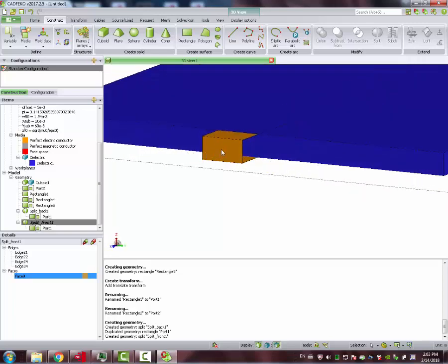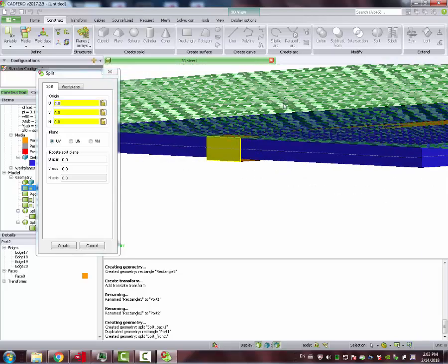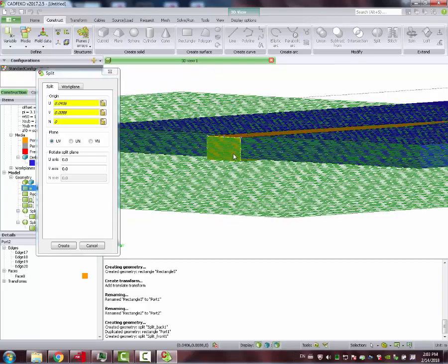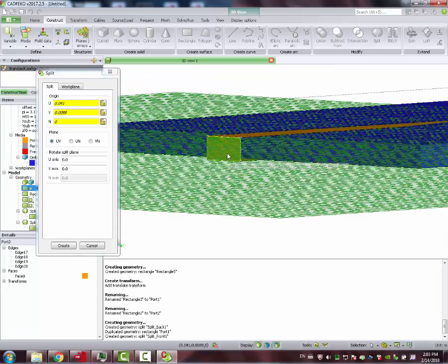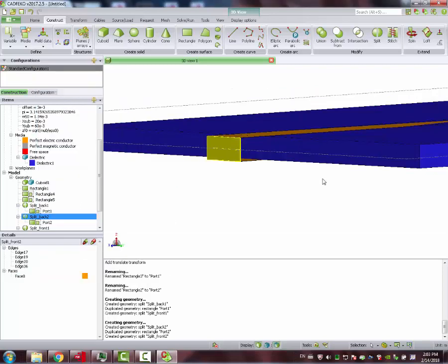Here, select the other part, split. We have to move it because a blade or a knife here is not going to cut anything. Ctrl Shift. You see here is stressed this middle point, double click, updated values here on the FEKO window, create, done.